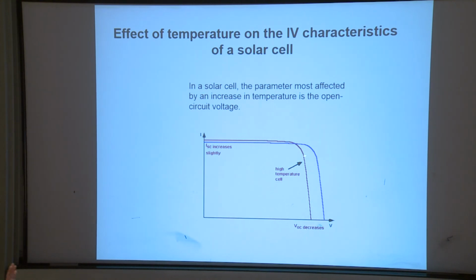So in terms of fill factor, which one is good? The blue one. That means you need to have the solar cell at as low a temperature as possible. Well, it depends on the location, where you deploy the solar cell panel. If it is a high temperature area, then the red one applies. If the temperature cannot be a chosen parameter, then we have no solution and always have to rely on the red one.